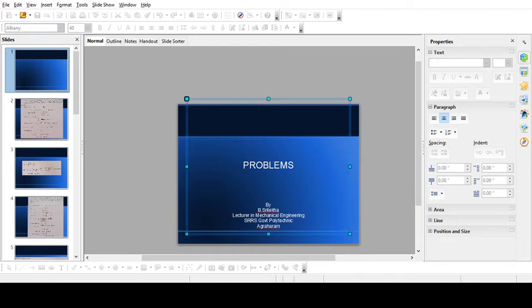So we are making use of the bulk modulus formula, that is direct stress by volumetric strain. We are given the direct stress and bulk modulus, so we can find volumetric strain from that. But we know that EV, volumetric strain, is simply change in volume by original volume, that is dV by V. We know that the formula for V is pi d square L by 4. So overall you can get the change in volume, that is 469 mm cube.